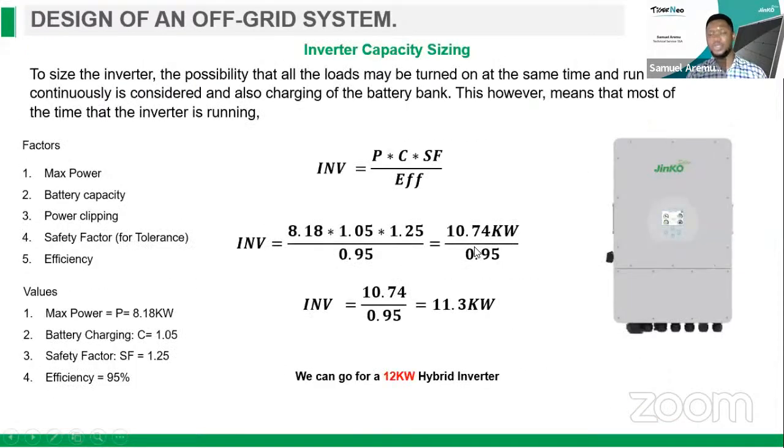what you need to understand is that the inverter has to cover the battery's voltage range. In most scenarios you have, let's say, from 40 volts to 50 volts, or 40 volts to 60 volts. Once the battery rated voltage, or even the range of the battery, is within the inverter's voltage range, then there's no issue. So in this scenario, we can also use the 48 volt rated inverter.